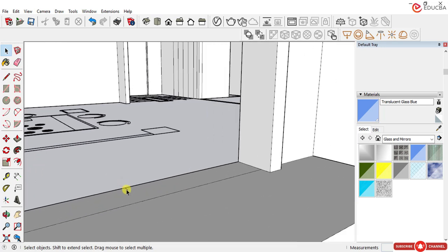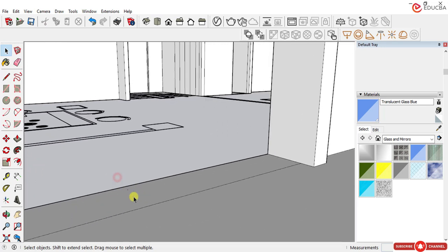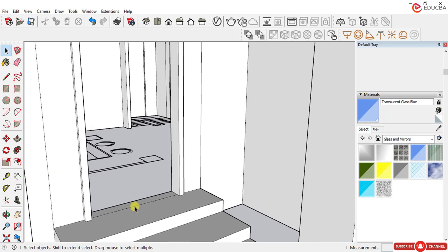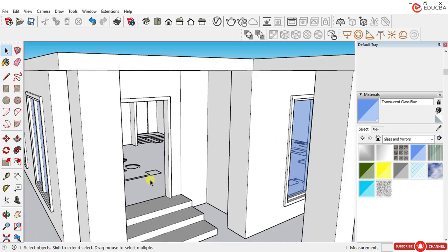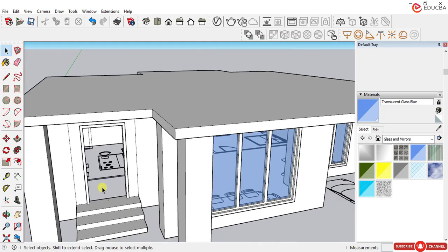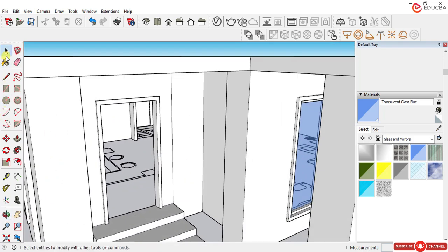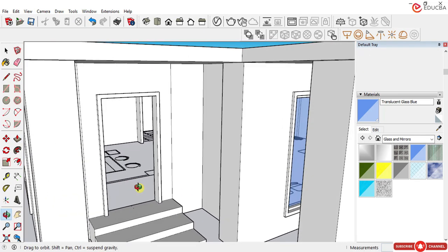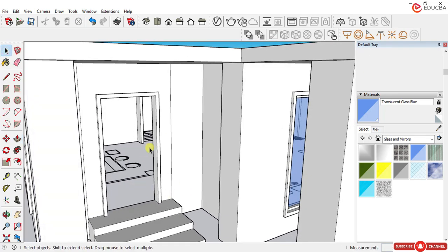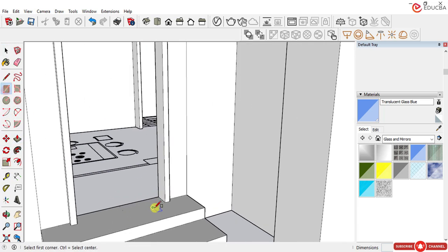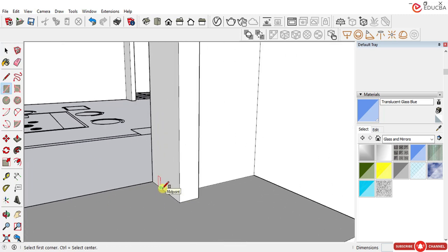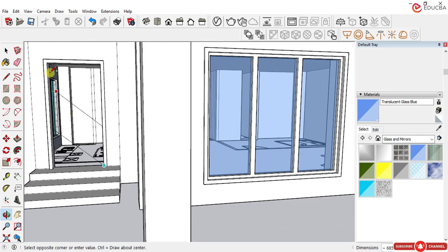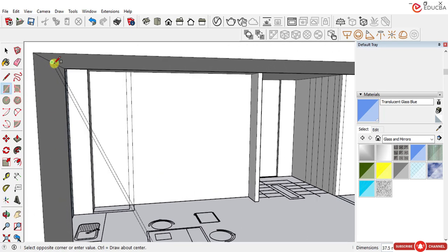Here as these lines, I have just provided the door frame. If we want to increase the frame, we can also provide 25 mm again. And now we need to provide the door for the same. Now with the rectangle, provide the rectangle from this midpoint to this midpoint.